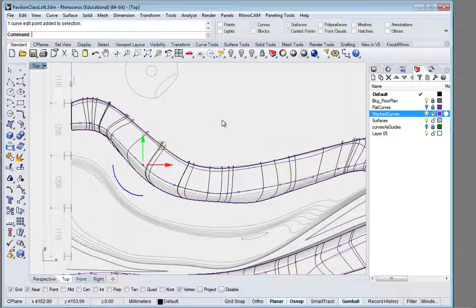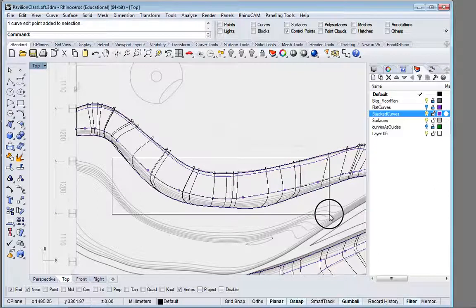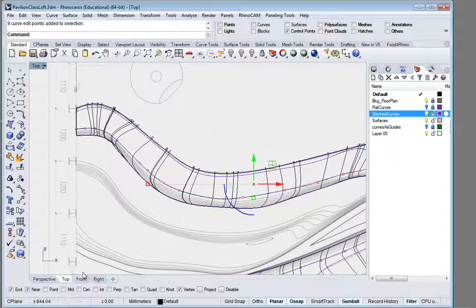Now this is where turning on this filter becomes helpful. So why don't we click on the filter? I don't want to be able to select surface, so I basically start to uncheck everything I don't want to touch. The only thing I really want is control points. So I'll make sure that's checked, and then I'm just going to uncheck everything else. So the only thing that I'm editing now is control points. So now when I click and drag a selection, the only thing it's going to select is control points.